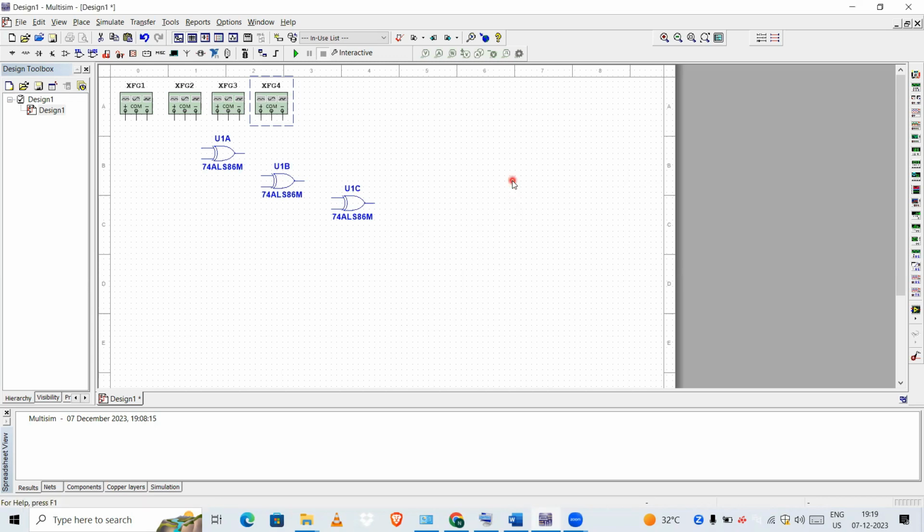So next, I'll connect this. I'll connect positive to first end, negative, positive of the second one to the XOR gate. Now XOR gate output, I'll connect to one input of the next XOR gate.